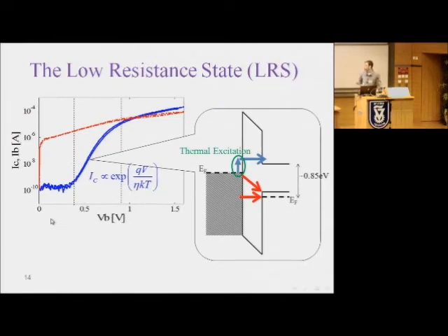But as we increase the bias into intermediate levels, we are measuring that the collector current increases exponentially with a Boltzmann factor. The reason is, if we look at the energy band diagram, you can see that the metal Fermi level increases, and the injection of electrons into the conduction band becomes possible.